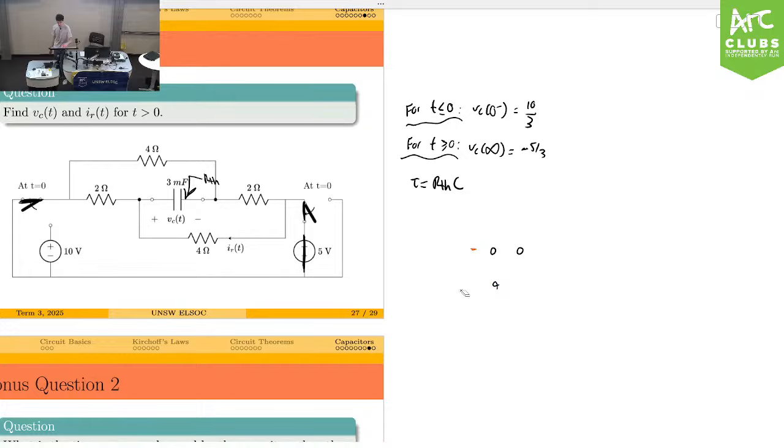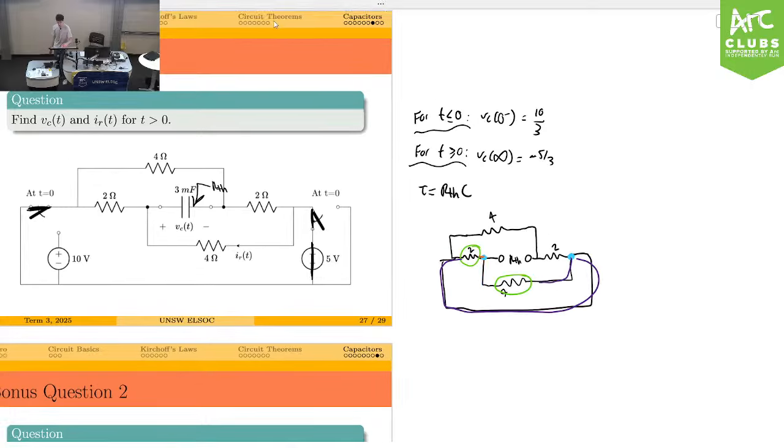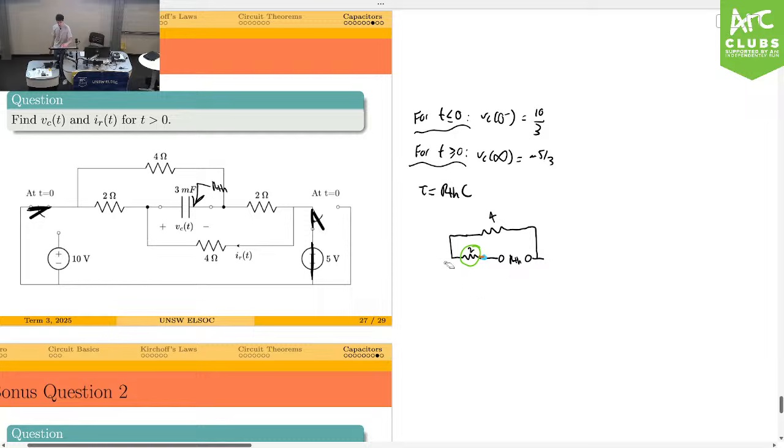Well, why did I rub it all out? Okay, that's fine. That's better. So if I simplify the circuit now, what it will become is something like this. That becomes in parallel with this, which is 2. So you get something like this. I've absorbed that parallel network into this middle node. This becomes 4 parallel 2, because I was connecting this one and this one, and this becomes 2. And now from here, you can see that this 2 is also in parallel with the other one.